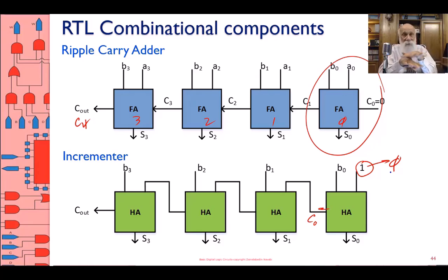If you put a 0, B passes through as is. No change. It puts some delay on it, but functionally no change. If you change 1 to 0, then B is added to 0. That means no change. So this becomes the enable for the incrementer. And so this is it. This is what I have for the adder.